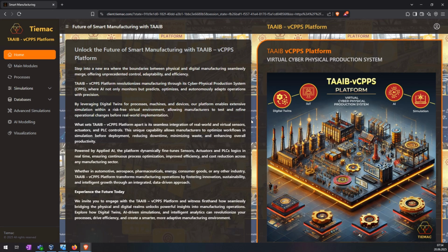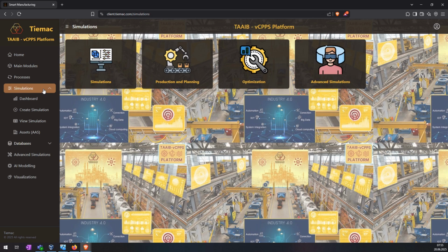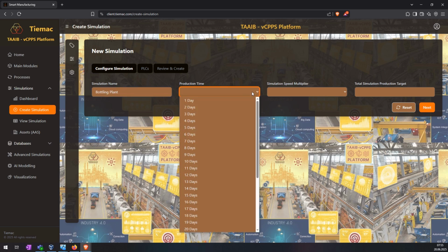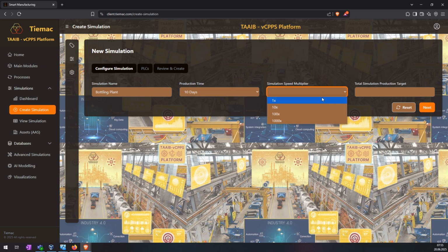Hello, in this video I'm going to create a simulation of the bottling plant. To do it, I will go to the Simulations tab and select Create a Simulation. I will enter the name of the simulation, define the production time for 10 days, speed multiplier 100, and total simulation production target as 10,000.